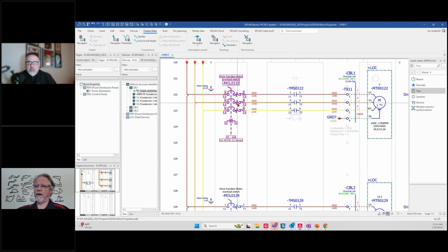When you show the next part, and it might be a page before, a page after, there might be another two connections, but because of the naming of them, they may become alphabetically connections one and two, and the first ones you placed are now three and four. So when you go to connection point one to look for something, it's now looking in a different place than you expected it to. So be aware of those.